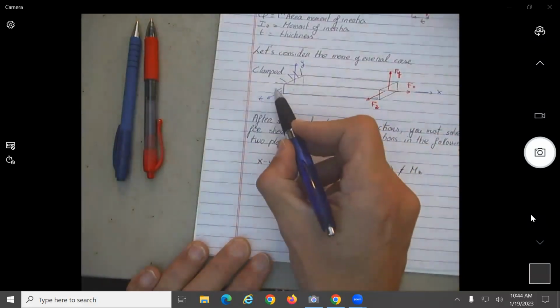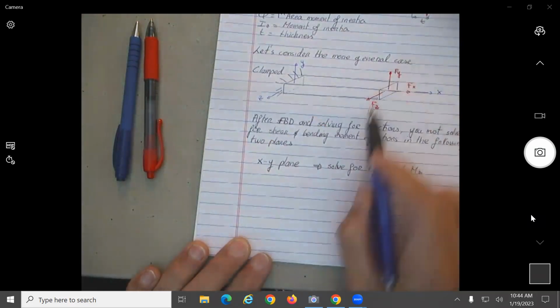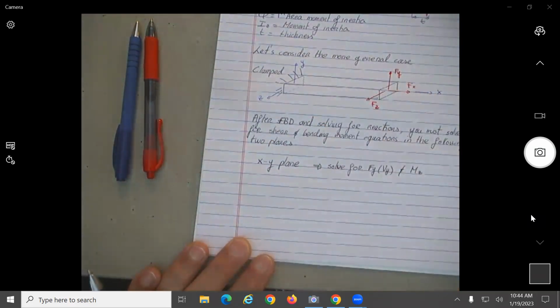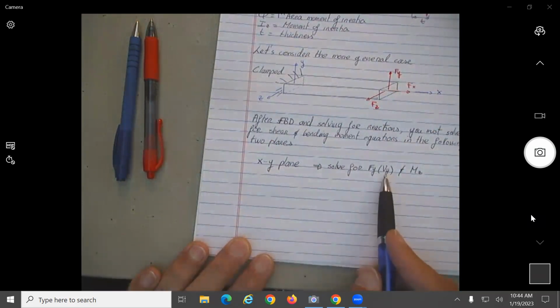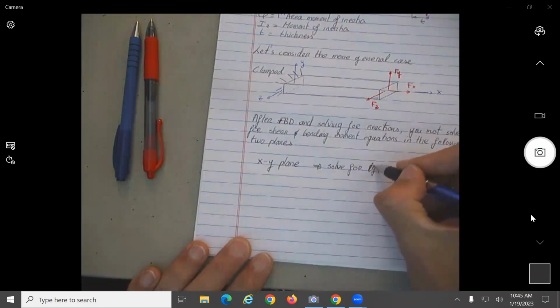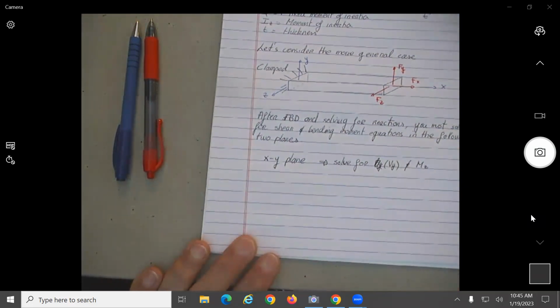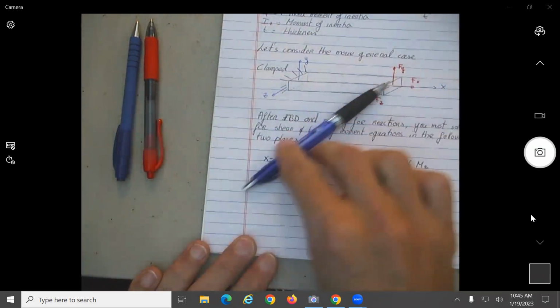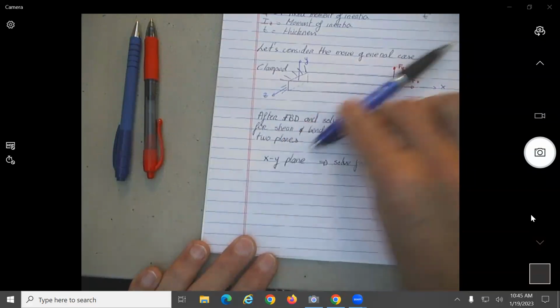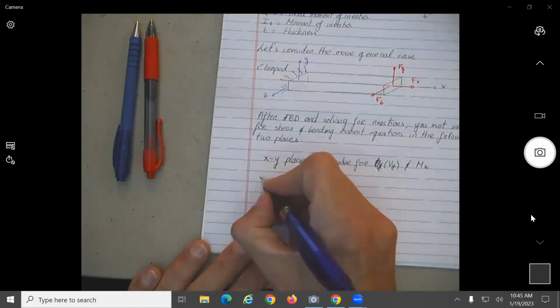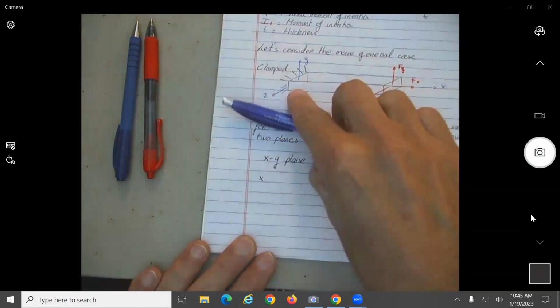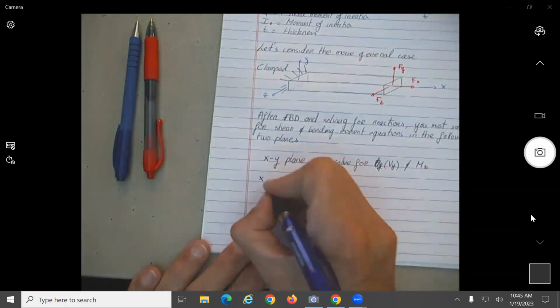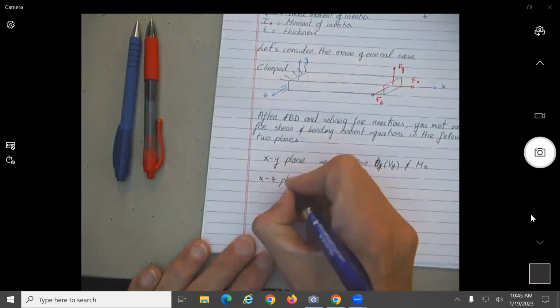If you move about the Z here, this way, no? This is going to bend up and down, no? Yeah? I mean, do you understand why I put Vy? Because the Vy will come from the Fy, no? Okay, let's put here Vy. I don't want to confuse. So now we look at the motion in this one. Next one, we need to look at the motion in this plane. So what is this plane? If we move this one, we always have the length. Now it's moving about the, so we look at the XZ plane.